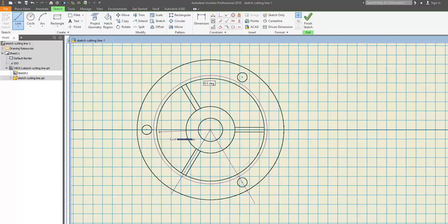Start the line drawing process one more time, and this is to have the part of the cutting plane. It cuts this part of the body in the radial direction. Okay, and then yes, one more line is needed, in the radial direction. It is at this stage to extend from here to there, to such a point. Press the escape button and then start the trimming process.